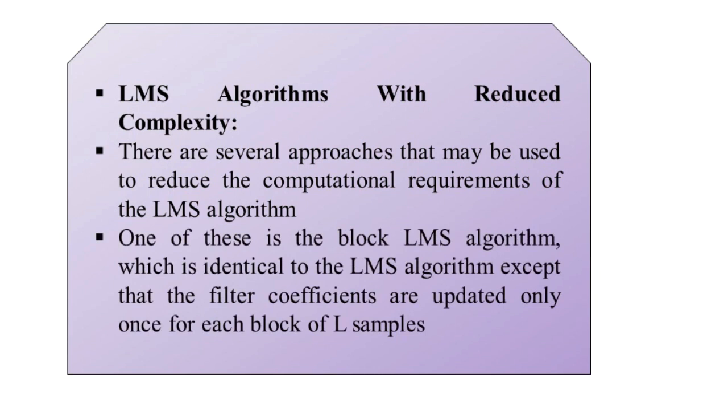In other words, the filter coefficients are held constant over each block of capital L samples, and the filter output, denoted by y of n, and the error signal e of n for each value of small n within the block are calculated using the filter coefficients for that particular block.